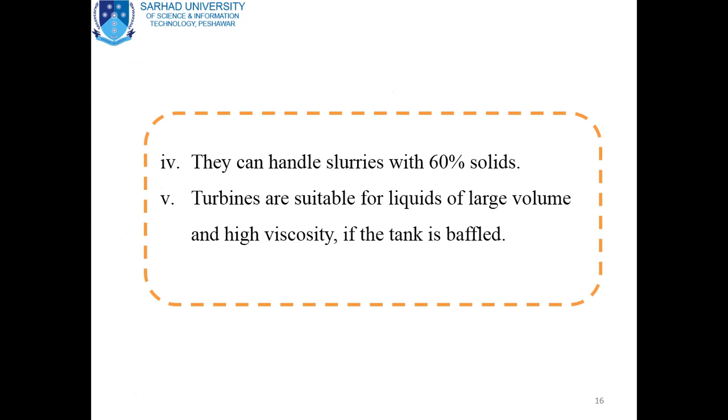Apart from these advantages, turbines can handle slurries with 60% solids. Up to 60% solid content having slurries can be mixed using the turbines. Turbines are also suitable for liquid of large volume and high viscosity if the tank is baffled.